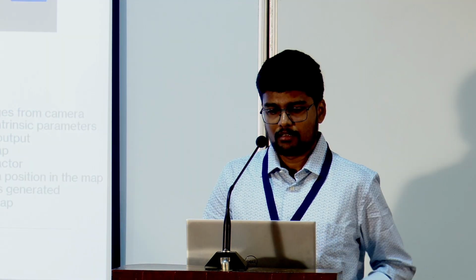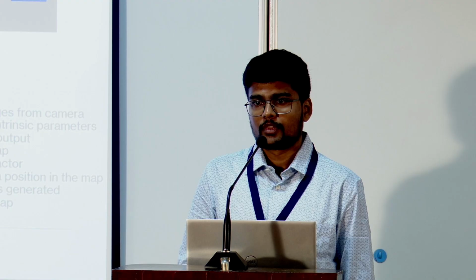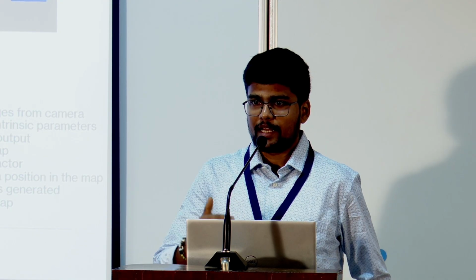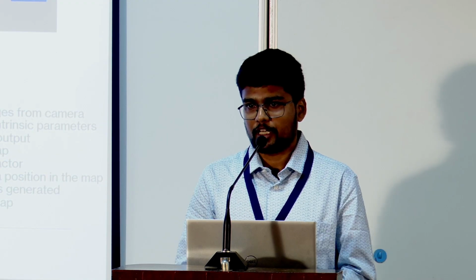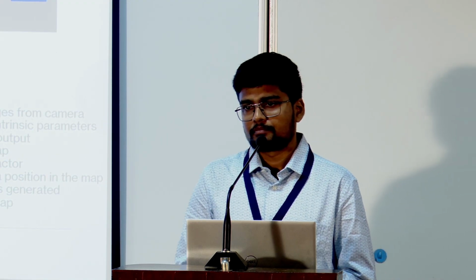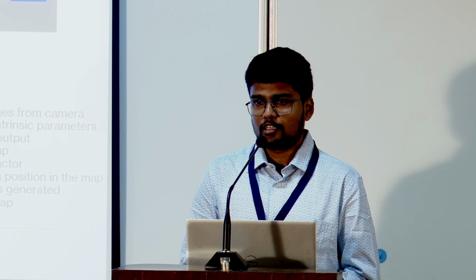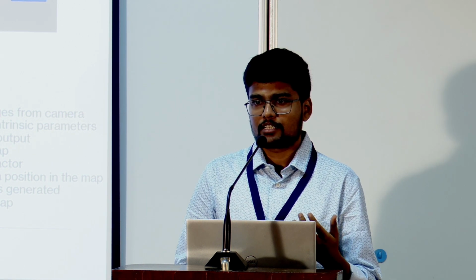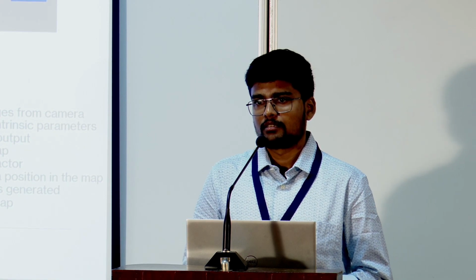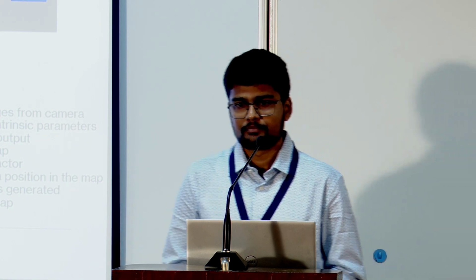For the LiDAR localization, you should know the map, right? No, we are creating the map, both the LiDAR map and the 3D reconstruction, at the same time. So you are running SLAM based on the LiDAR? SLAM based on the LiDAR, yes, and then the 3D reconstruction from the Gaussian splatting. Okay. Thank you.